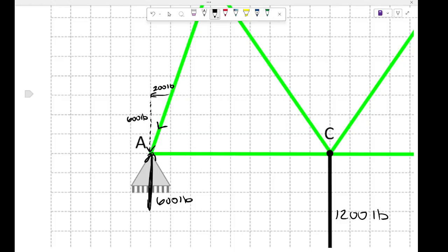And when we look at the forces vertically, the 600 pounds now balance, but that 200 doesn't balance. And the way to balance that is going to be to have a force to the right of 200 pounds by joint AC. So that's going to identify that AC is pulling on that member to the right. So you have AB pushing down and to the left and joint AC pulling to the right. So what we can do here now, we've identified what's happening here.